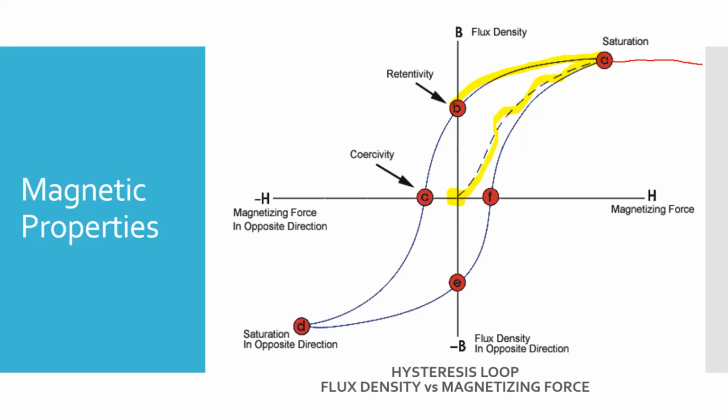If we were looking at aluminum, it would go almost all the way back to zero. But in a ferromagnetic part, the type of parts we're going to test, you can see that for that split second where the current goes to zero, it maintains a certain amount of magnetism. And in fact, it's retaining almost 2/3, most of the magnetism, right?